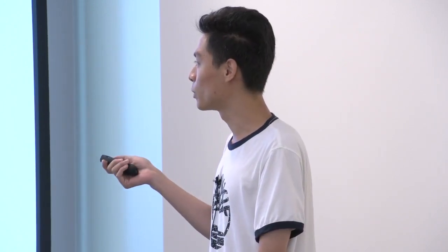Are the dashed parts of those lines inferred or extrapolated? Yeah, it's extrapolated. I see why for the blue line you had to extrapolate into 3 years. Why in the orange line did you have to extrapolate down to short? It seems like that should be the easiest. So it's because the early retention is not a problem in planar NAND. This is from old data, so we didn't focus on the retention error that appears in a very short time after programming. We usually care more about the long-term retention in planar NAND. That's why we didn't have the data at that time.